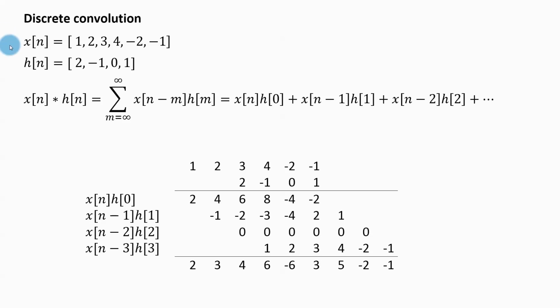In the previous examples, MATLAB was computing the convolution for us. But what if somebody gave you this signal and this impulse response and asked you to compute their convolution by hand? These things have been known to happen, especially in your tests. So how would you go around it? Well, you just need to write down the definition formula for the convolution and evaluate it. Especially with that simplification that I told you, which you can use when your impulse response has a finite number of non-zero values, you can write the convolution like this. And actually this is how MATLAB is computing the convolution.